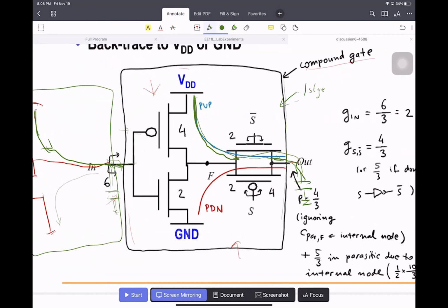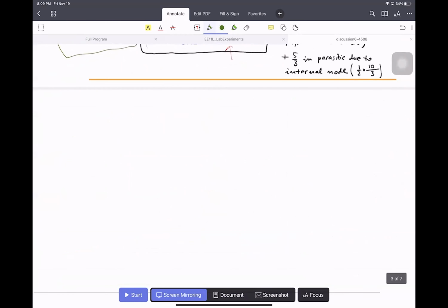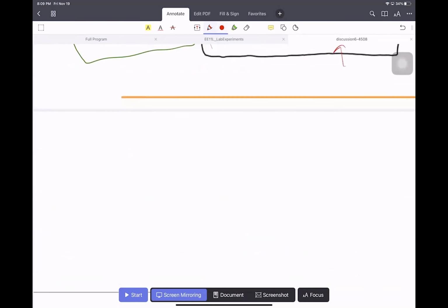So what is the transmission gate? Basically, when the transmission gate is off, it's an open circuit, there's nothing there. But if it is on, it's just two transistors in parallel. In this particular example, there are two sides of two, one side of two NMOS and one side of two PMOS.